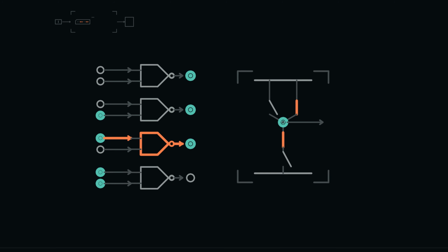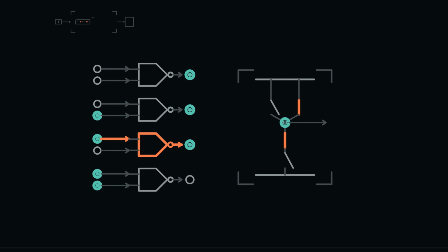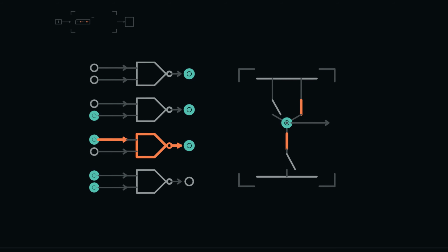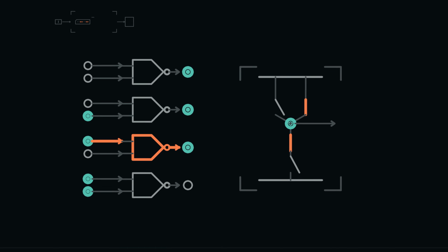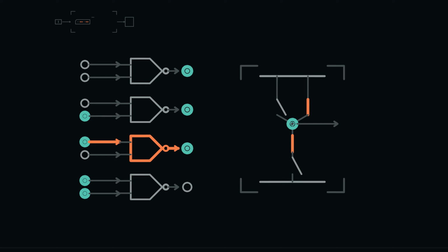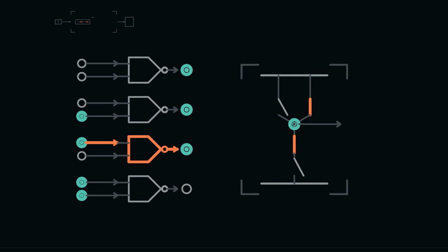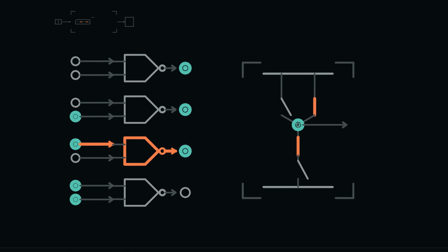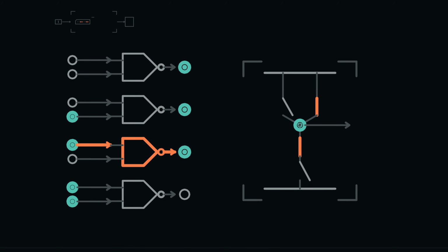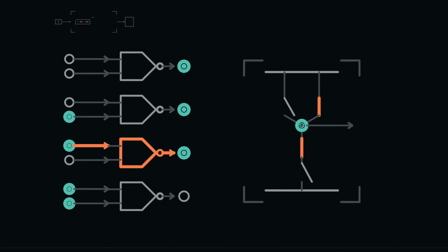Now feed the same input into both NAND entrances. When that shared input is 0, the pair is 0 and 0, so the output is 1. When the input is 1, the pair is 1 and 1, so the output is 0. The output is always the opposite of the input. One NAND has therefore made NOT. This is our first constructive step. We did not merely claim that NAND can imitate another rule, we traced every possible input to prove it.